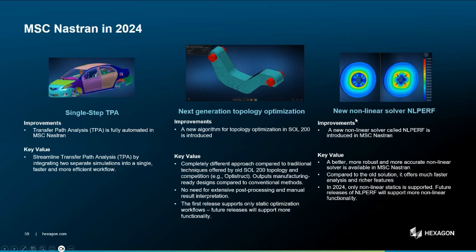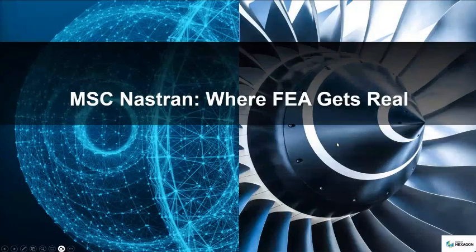And then the last one, which we covered in the previous section, was spending some time and effort on tweaking Nastran to run faster. So activating this NLPERF setting inside of Nastran was all for nonlinear analysis. And that brings us effectively to the end of the presentation. So thank you all for listening, and let me know if you have any questions.